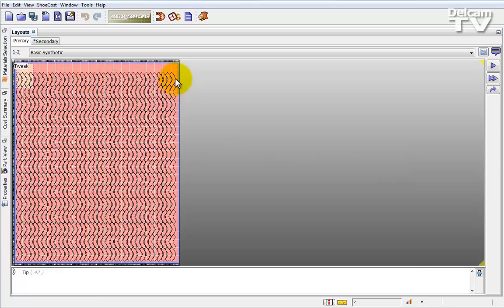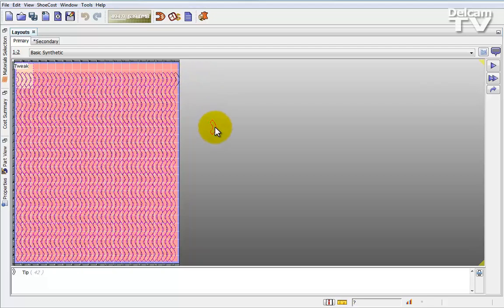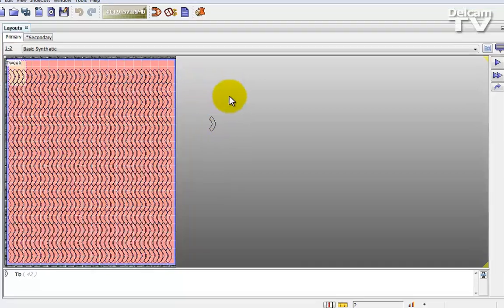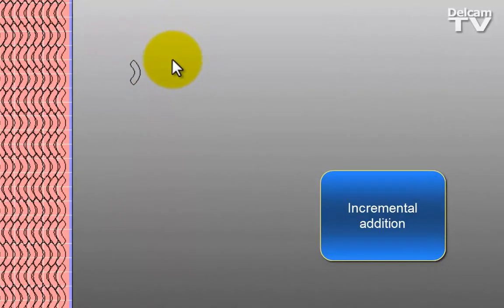Full manual nest mode. If I wanted to take a part, for example, let's take a part here. Repeat, insert and move. Here we've got a single part. I'll demonstrate it here rather than in the whole nest. If you click on an empty space first to reset the operation, we click a part, we insert, gives us another part. Now we click on this part, we can move it. Let's just zoom in so we can see this a bit better.